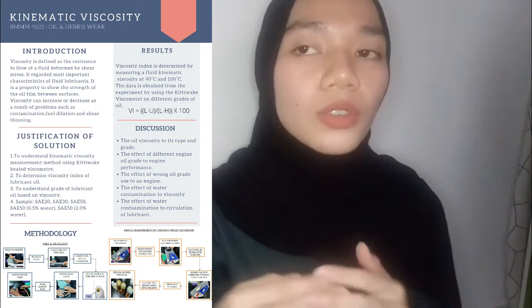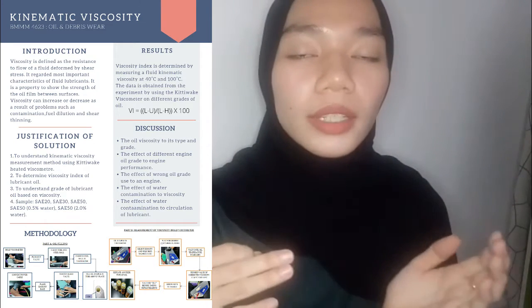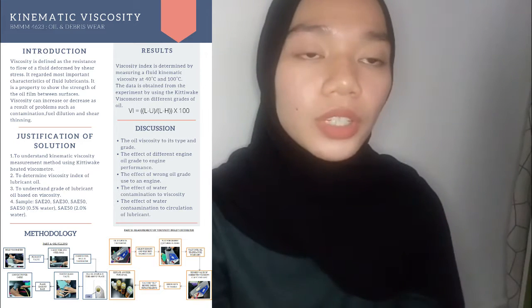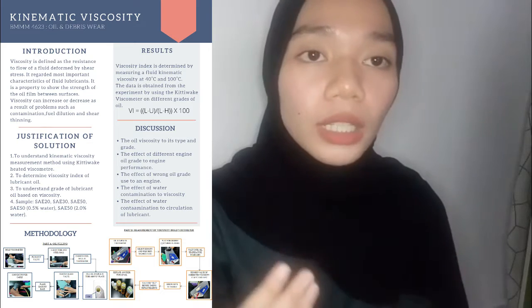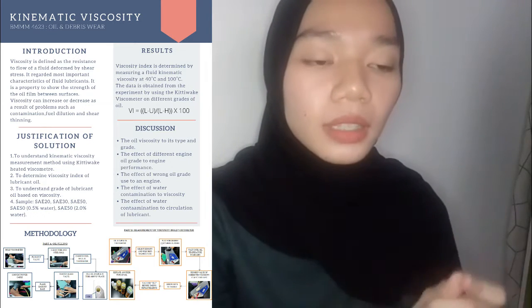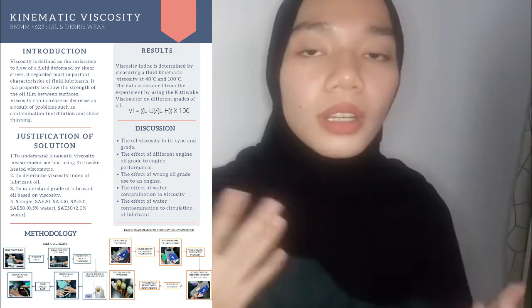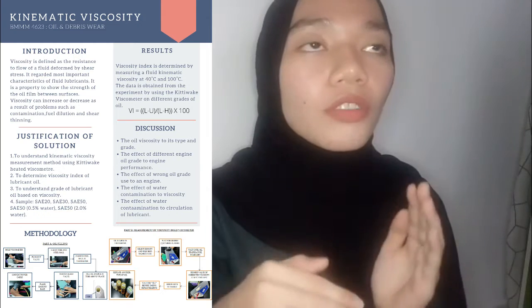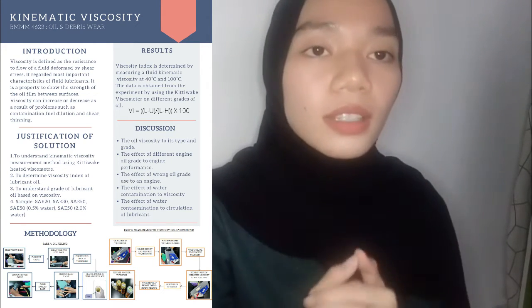The viscosity is usually chosen for optimal performance within the required temperature. The temperature dependency of oil can be determined by calculating the viscosity index. It is an empirical parameter that compares the kinematic viscosity of different oils, showing the sensitivity of viscosity to temperature.